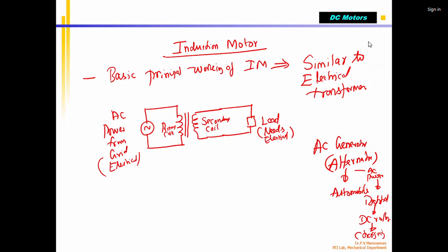Correct? In any car or automobile, you have a battery which is used for the spark plugs, the bulbs, or any other motors, the fuel pump. Most of the devices inside your car, motors, solenoids, or spark plugs, require a DC voltage, which is supplied from the battery. So the battery is a DC source, and once you start using the power, the voltage drops. After some time, when the voltage becomes lower than a certain level, it has to be recharged. For that, you are using the alternator.